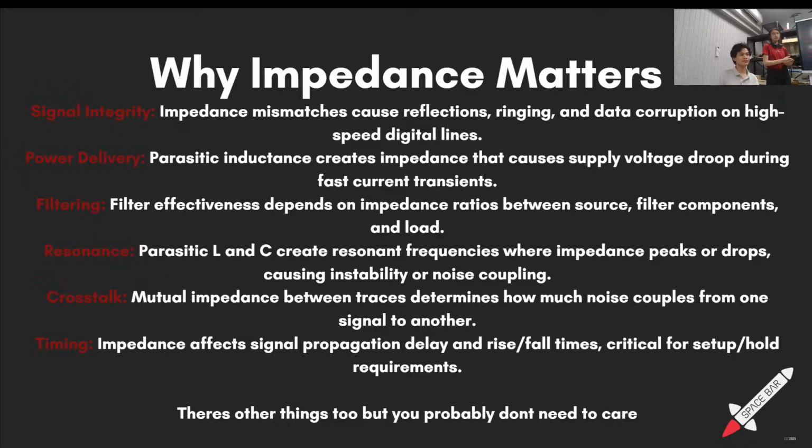Anything else? Okay, this is going to sound weird. Basically, an inductor becomes a short circuit, and a capacitor becomes an open circuit. You can see the symbol. In DC steady state, that means when the voltage is not changing at all.